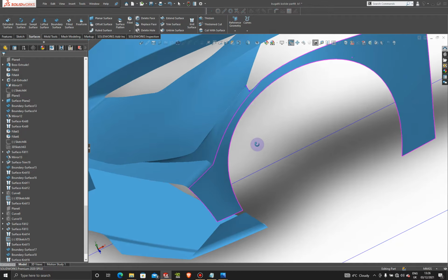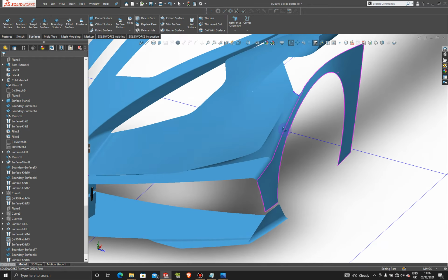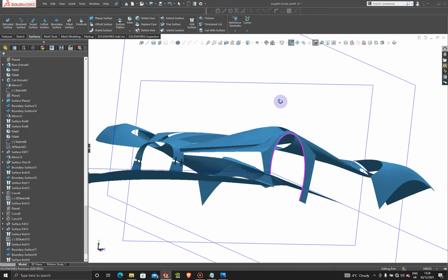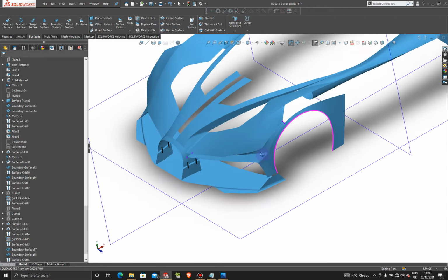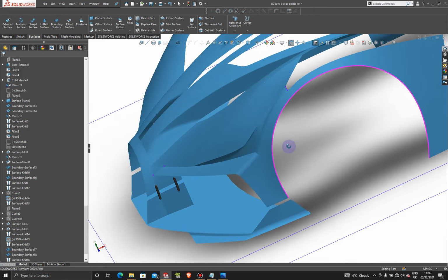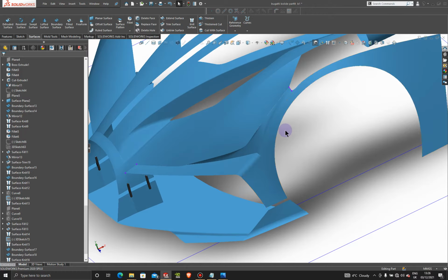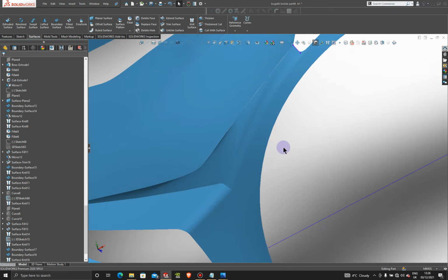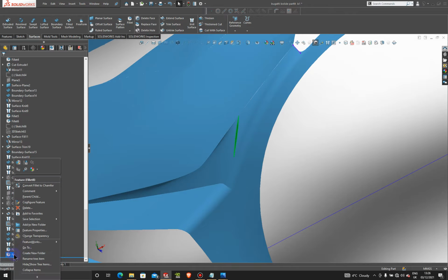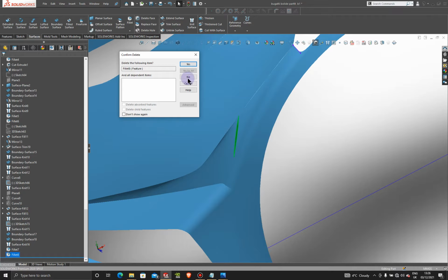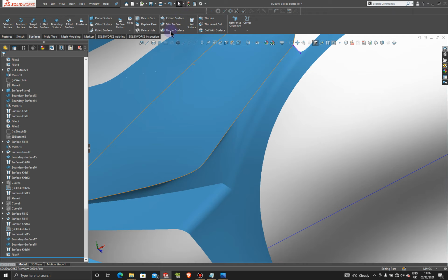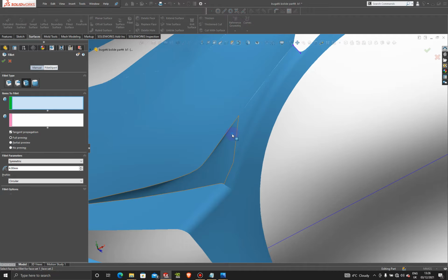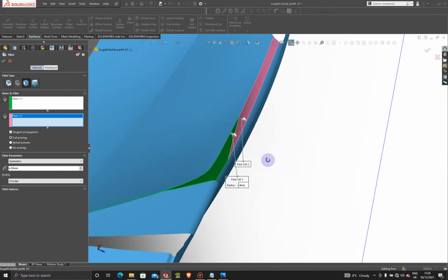That's what we're going to do with this surface, and then we'll probably come back in the future. Let's just try something here. Delete this fillet here, and let's try a face fillet. Face fillet, and let's choose this face, and then this face, and let's turn them inside.